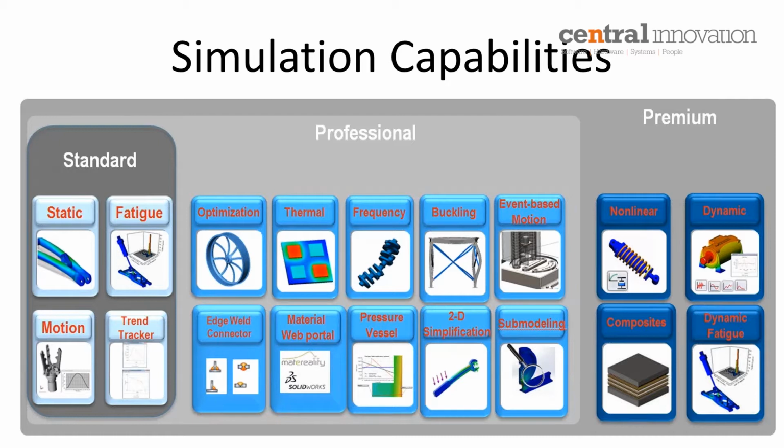Okay, now today I'm going to show about Load Case Manager and Design Study. Design Study is available in the standard packages and also in the CAD Premium package, but the Load Case Manager is available on Pro and Premium simulation licenses. So if you don't have a Simulation Professional or if you don't have a Simulation Premium license, you can't use Load Case Manager, and also you can't do optimization. Optimization is an advanced option which is available inside Design Study. I'll talk about that later.